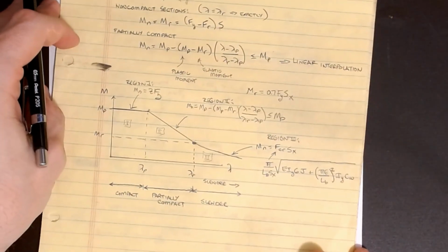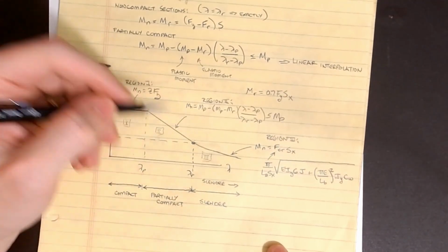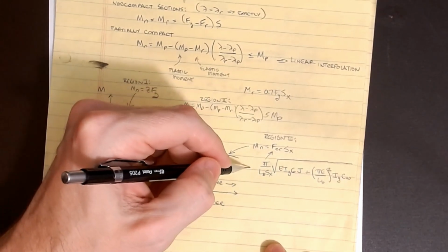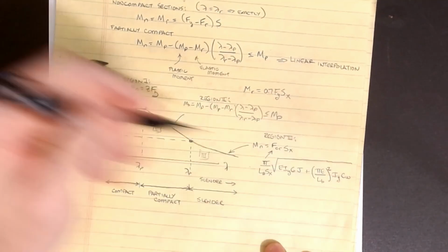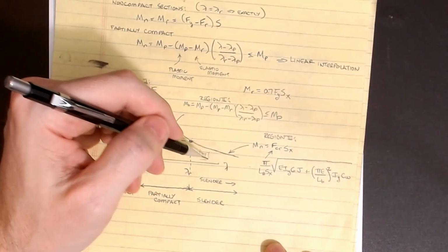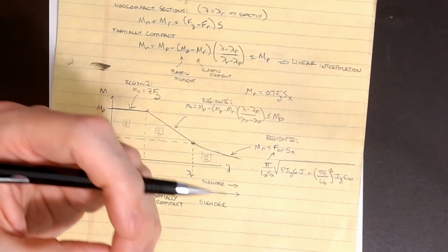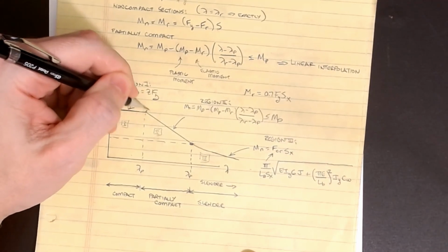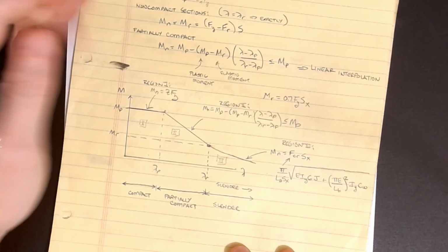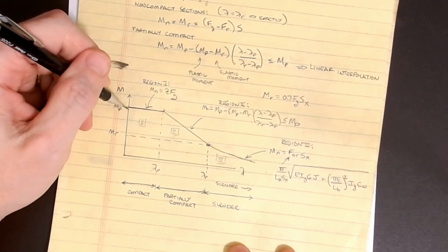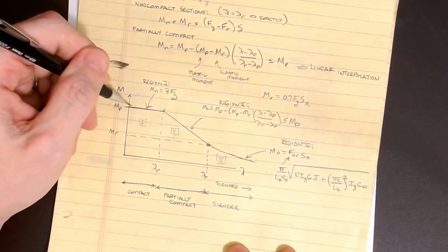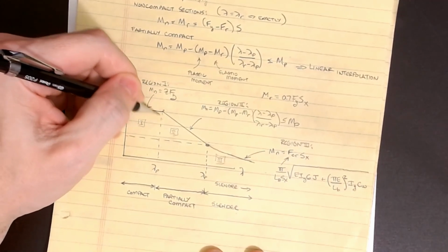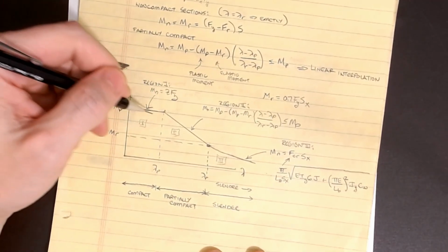Now, from a design standpoint, you never want to be designing a beam out in region 3. If this thing gets too slender, it basically goes into no strength and it's asymptotic, almost at 0, way out there. You're giving away so much material that the stability of your beam means it can basically carry very little load. So the optimal point is to be around here, as close as I can get to that anyway. If I'm over here, your beam is so over-designed that you're paying a lot of extra money for a really heavy member that's not needed. Whereas if I'm over in this region, it's a little bit more economical. This is the most economic spot to be looking at.